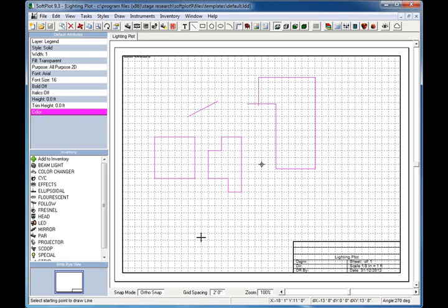If I hold the control key down, plus the left mouse button, it now starts there. And as you can see, the snap is totally suspended. So I left the control key up. It's now snapping. So I can go snap, snap, turn the ortho off temporarily using the control key. Come over here, turn it back on.